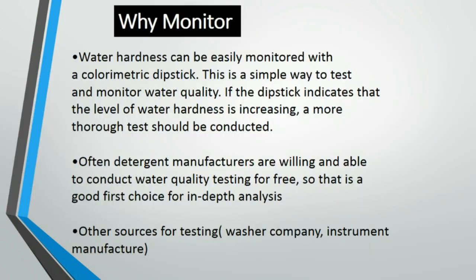So now, why do we monitor? Water hardness can be easily monitored with a colorimetric dipstick. This is a simple way to test and monitor water quality. If the dipstick indicates the level of water hardness is increasing, a more thorough test should be conducted. But that means there are truly simple and quick ways to do it.